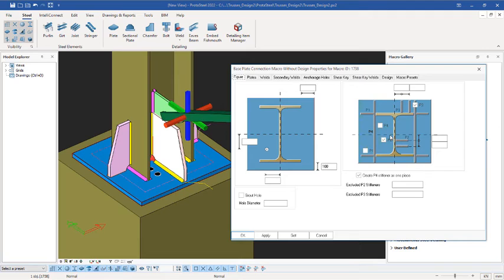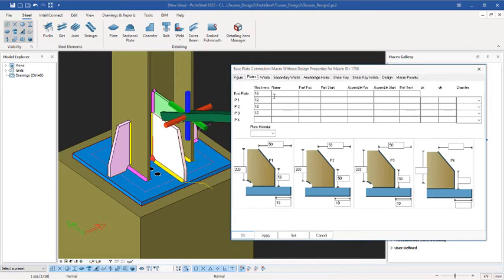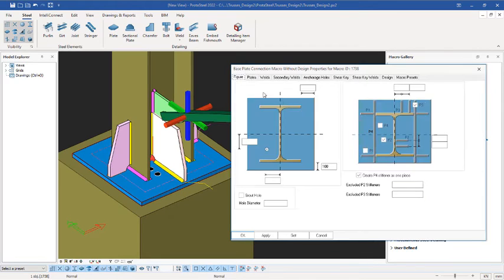And then I unchecked P4 and stiffener P4 and stiffener P1. The stiffener is supposed to be at the edge here, and the one that's supposed to cut across, I wouldn't need those ones, so I have to get rid of that. So if you get to the plate itself, you can see here we have the thickness of this plate to be 16 millimeters. So the thickness of P1 is 12 up to P3. We wouldn't have P4 because we have removed it here.